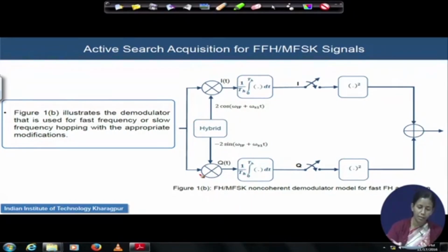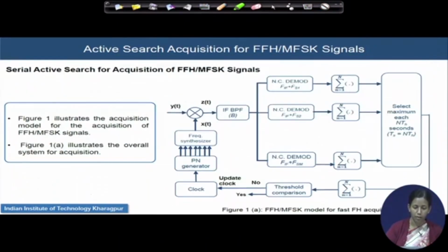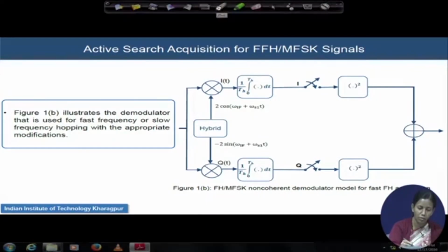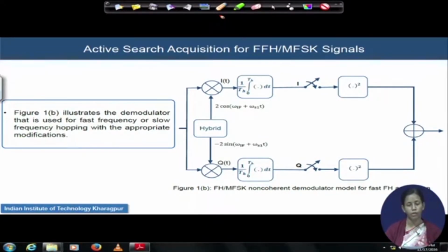That incoming signal here is from the output of the band pass filter. So, remember the signal bandwidth will be capital B only, and here is the integrator. The integrator is expected to integrate the whole signal over a duration of hopping time. So, it is 0 to TH for both the in-phase and the out-of-phase carrier.